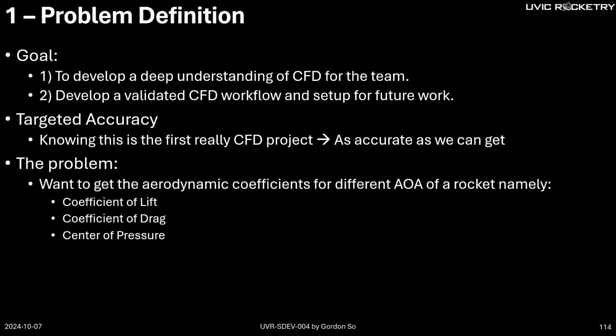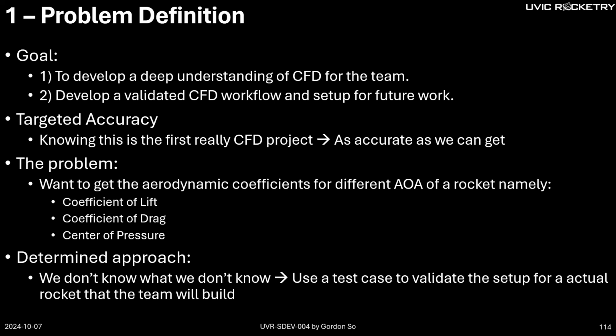CFD allows you to do further analysis than just empirical models. That's one of the biggest things that we want, because we know supersonic flow is really finicky in most rocket trajectory software. So the approach I determined is, one, the team doesn't know what we don't know. So let's just use a test case to validate the setup and then apply that setup to the actual rocket.